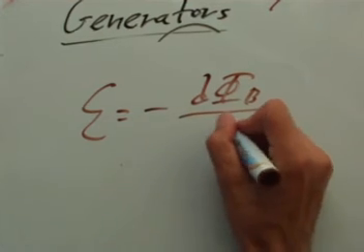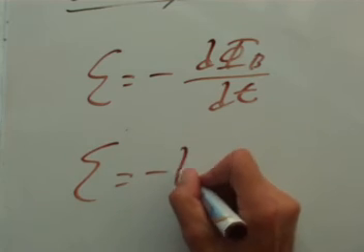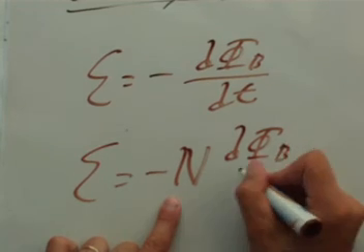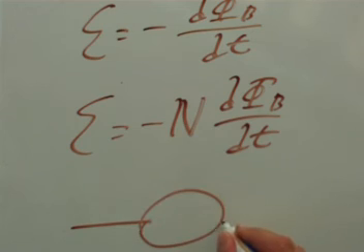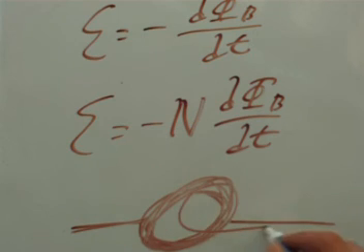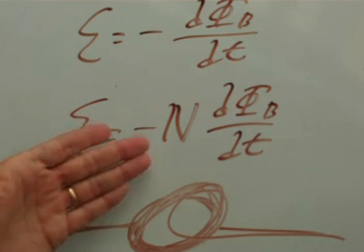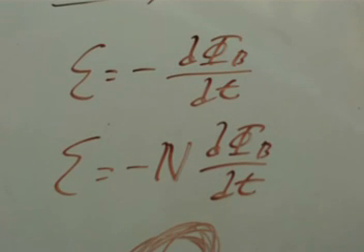And the other thing that we glossed over is that there is this version of Faraday's law, the change in flux with respect to time. You don't always have to build your loops out of one loop. You can have many loops, which commonly has a symbol N in there. Whatever one loop does, two loops will be twice the magnification. So instead of just putting one loop in a magnetic field like this, why can't you take the wire and spin it around thousands of times like that? So the induced EMF you'd get out would be 1,000 times the amount. Not a really strong contributing factor, it's just a linear factor, one for one in there. But nevertheless, Faraday's law does have a number of turns parameter in front of it in some cases. So there you go. There's a ramification of Faraday's law and how that changing angle can produce an EMF.